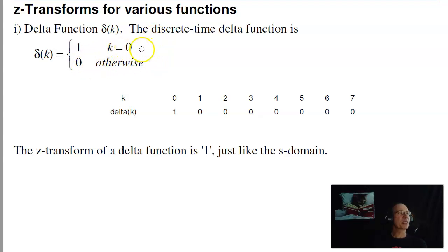In the s-plane, I had the lookup table for delta function, step, and I think a damped sine wave. Same thing as z-plane. Let's start out, let's just assume that the z transform of a delta function is 1. When you took signals, there's a proof of that. We'll just kind of take that for granted now. What a delta function means, this is 1 at k equals 0, 0 otherwise. That's a delta function. Z transform is 1.